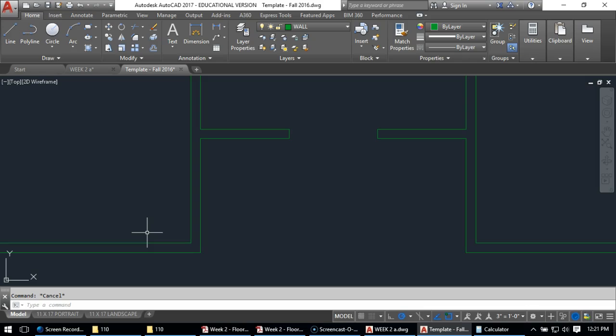I could figure all that out in AutoCAD if I wanted to do that. But I think what I'll do is I'll just assume that it's centered point of this wall, so that when you're in the space, everything looks nice and centered. I'll hit enter. Now, if this were a real drawing, the contractor might have to ask for clarification on those points, since you could have different interpretations. But I'm going to start from the midpoint of this wall, do the same thing like I did on the other side. I'm going to start there and click enter to draw the line.